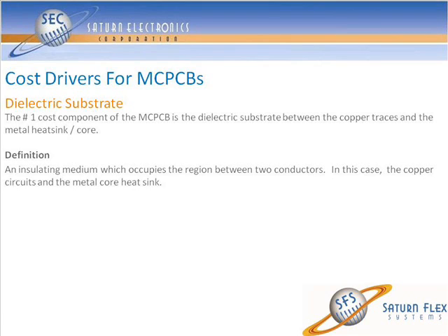You're ranging for that tiny thin piece of dielectric, probably $30 to $40 on the multi-purpose ones. Standard FR4, to put it in perspective, might be $3 to $5. So think about how much value is in that dielectric that you're paying for when you're specifying a particular product. And think about what you can do to reduce that cost. It's your easiest target.